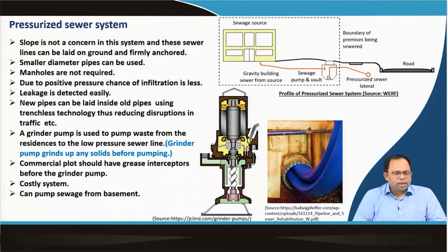So, one thing that usually happens is whenever we are trying to improve a particular sewerage network, or a city has an old sewer network, like you can see that this is the old pipeline, and now we want to augment this pipeline or rehabilitate this sewer system. That means, in many cases we need to upgrade the sewer system. So, it is very difficult to start constructing a totally new pipeline. For that we require extra space and so on. So, one way to go around this is to use the existing pipeline and put another conduit inside it,